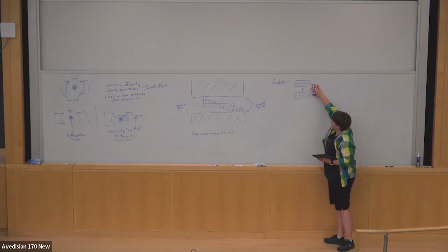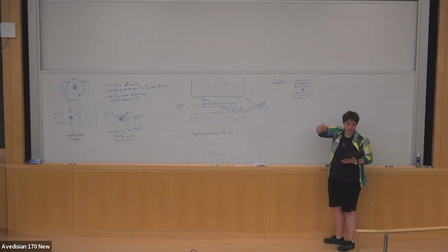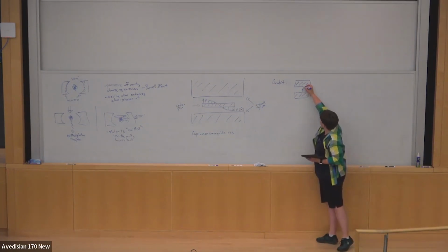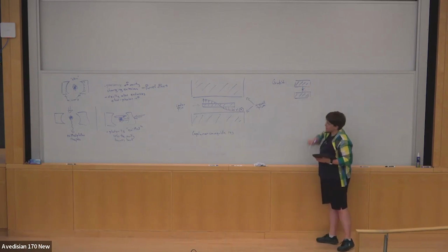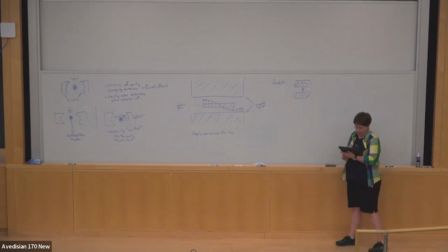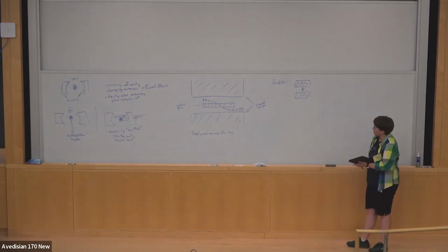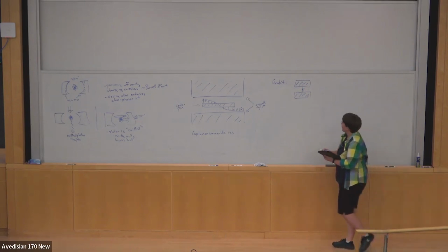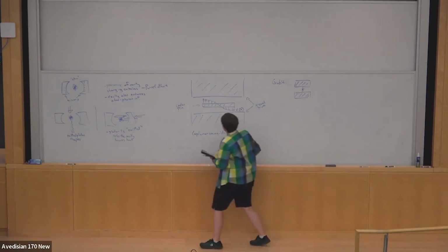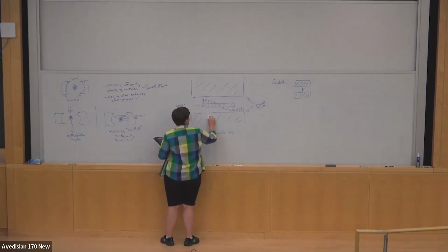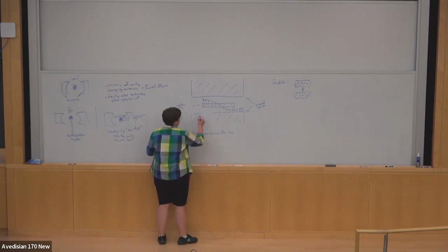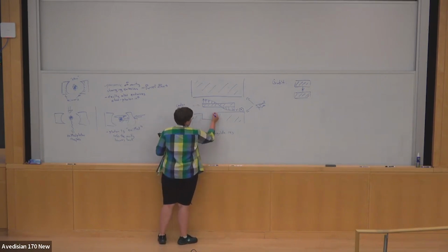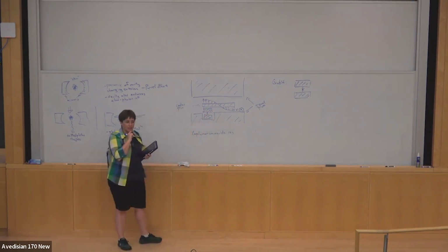And so these two pieces of metal form a capacitor that sets EC, and then you run leads between them interrupted by a Josephson junction. And so what you can do is just make it fit. So you cut out a pocket from the ground plane and fabricate the transmon inside of here.